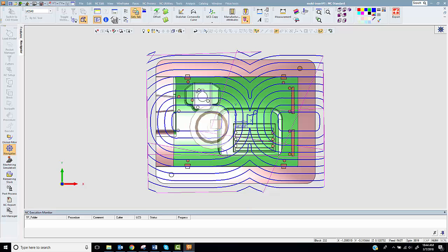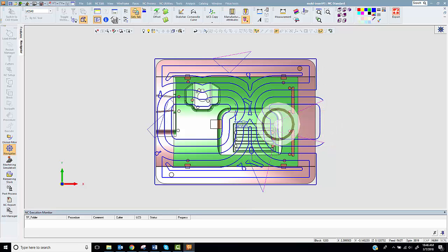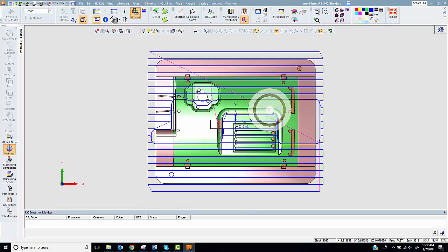The user can also define climb milling only, shown here with the system optimized strategy of stock spiral. The user has the ability to define basic spiral strategy as outside in or inside out with stock offset passes against the part. And as the last option in this video, the user may choose a parallel strategy, bidirectional or unidirectional, with the climb final pass against the part.